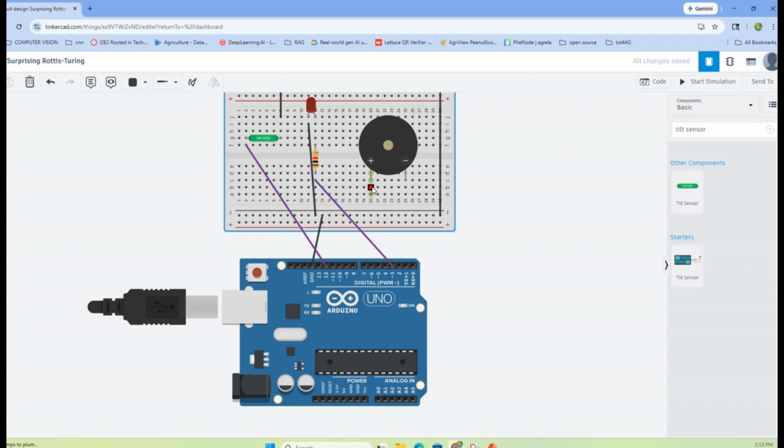The piezo buzzer will have two different ends, a positive and a negative one. We are going to connect the negative to the negative rail of the breadboard, and then we have a positive pin which we can connect to any of the digital pins. I'm connecting it to pin 2. Again, you can connect it to any of the pins. In addition to session 1 and session 2, we have just included a buzzer here. This buzzer is going to act like an audible alert for the threshold.